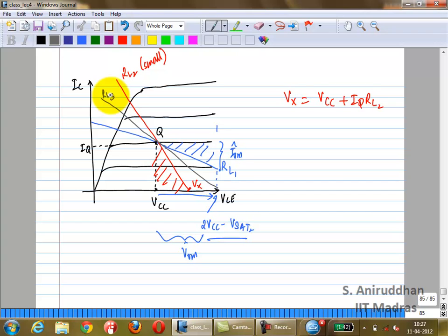In a real case you would have to change IQ such that that will be the design parameter. But in this case we keep IQ constant and vary RL, because that's what we have been doing. If you do that, you will simultaneously maximize both the voltage and the current. That will be the point when Q1 just cuts off, but also the point when Q2 just goes into saturation.